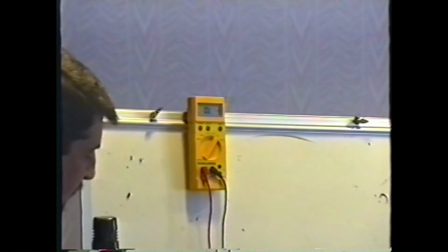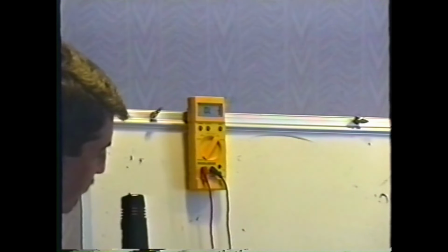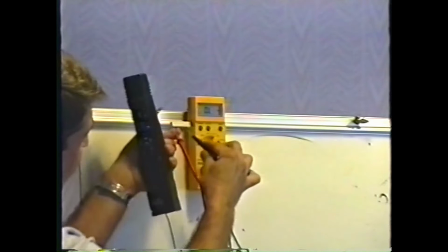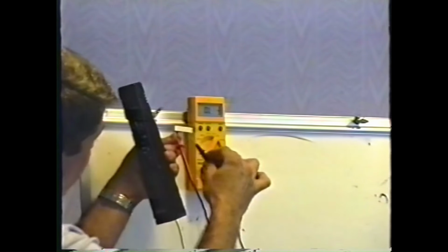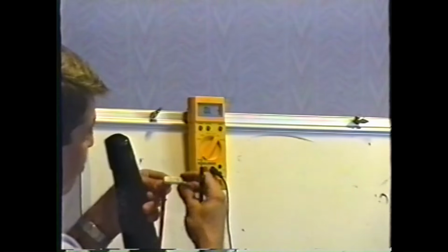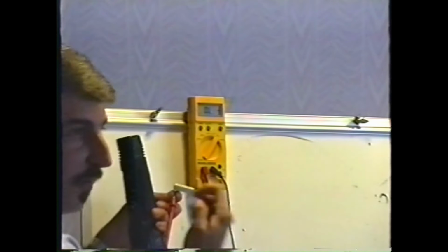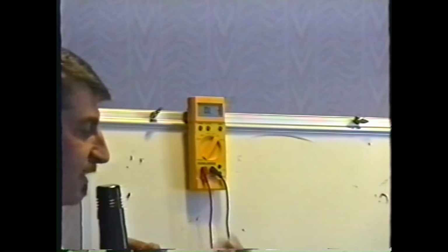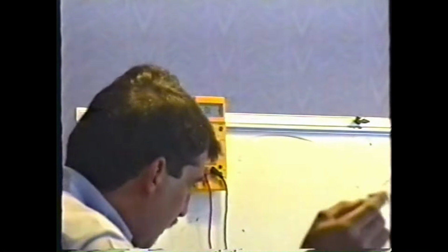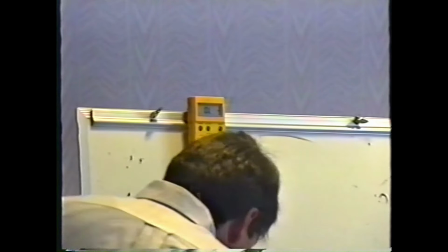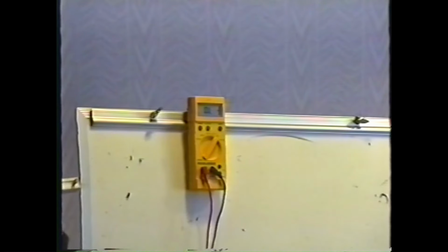Oops. If I'm not touching it with my hands, that is. That's why it's important to keep your hands off the meter leads. You see the meter says OL, open. Just as if I'm not touching anything at all. It's supposed to be 2 ohms. It says 2 ohms on it, but it's open. And it even says on the back of it, open. So always pull your resistors out. If they say open on the bottom, they're bad.